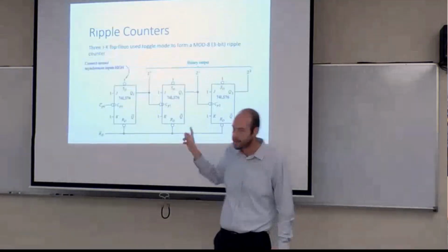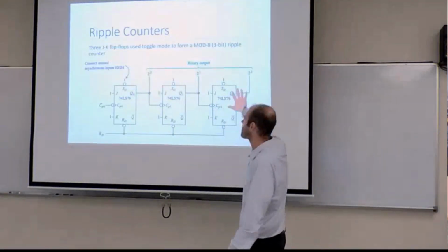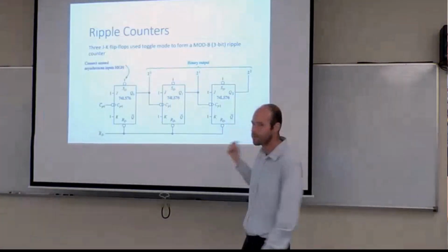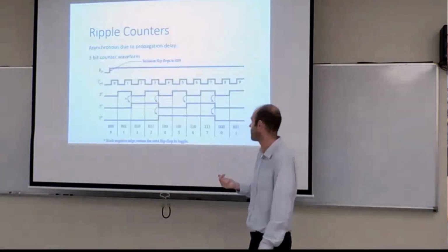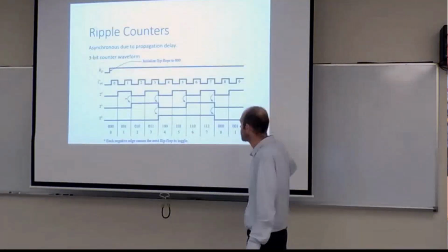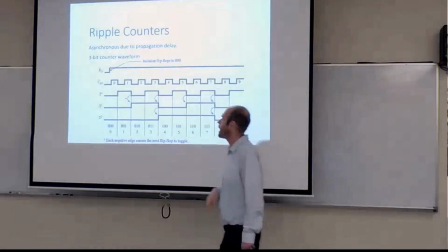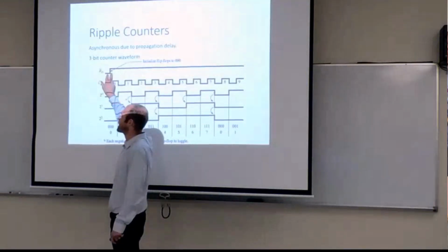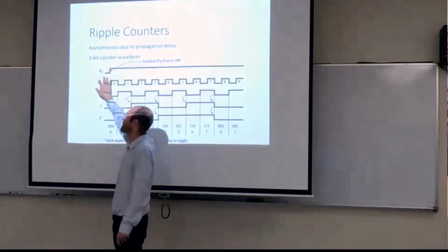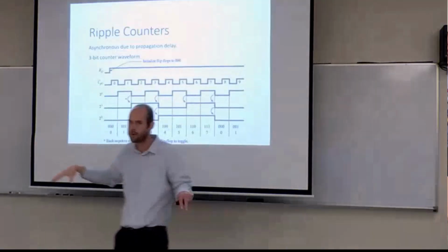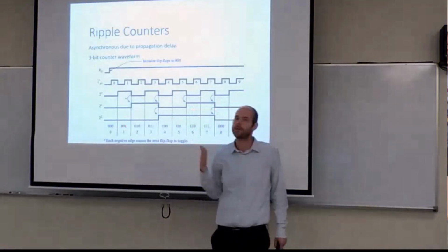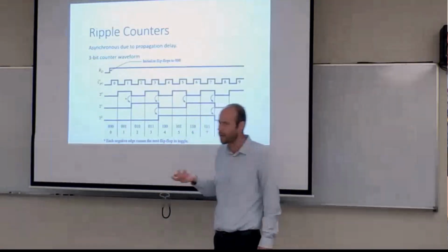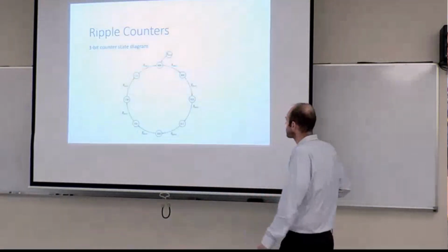So physically, this counter will count up from 0, 0, 0 to 1, 1, 1, then roll over and continue counting as long as that clock is going. So this is a mod 8 counter. A lot of our notation will have a reset, just a brief reset activation right at the beginning, and that's going to just start our count at 0, 0, 0. For our software purposes, it will typically automatically start at 0, 0, 0, or maybe 0, 0, 1, I saw in a few instances.